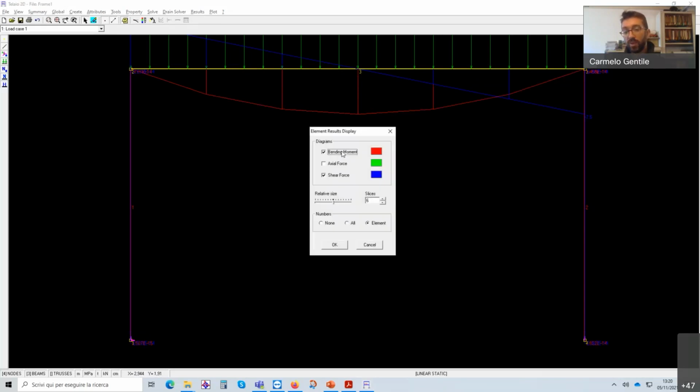That's why when we want to find the maximum bending moment, we have to find the place where we have 0 shear force, which is a simple equation to solve.